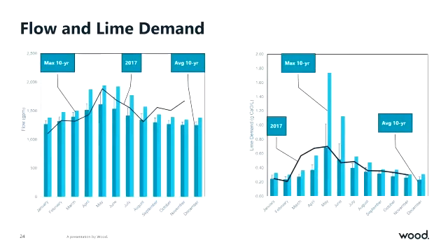So a lot of data here. Big takeaway though is this shows the flow variability that we had to manage. We designed the temporary treatment process for a 1-year period of time. You can see we had quite a bit of variability with some pretty good peaks around the spring freshet, which we saw around June timeframe, sometimes back here in May as well. And that'd be accompanied with a big increase in lime demand, a big increase in metals concentrations as well. So much more sludge generation and sludge management requirements.